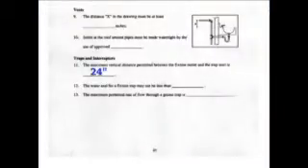Number 11, the maximum vertical distance permitted between the fixture outlet and the trap weir is what? Now, the trap weir is where the trap comes down, goes back up again, and begins to go horizontal. In other words, where the trap begins to drain. That height. So from the fixture to that height, what is the maximum that you're allowed? It's 24 inches. Go ahead and write in 24 inches.